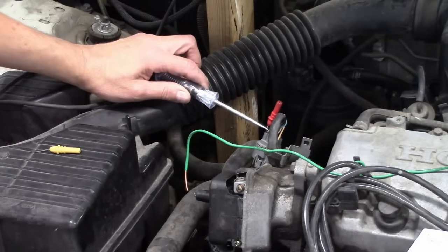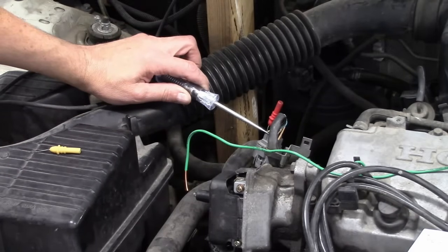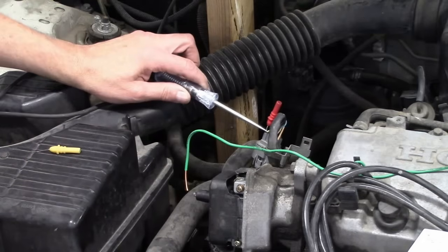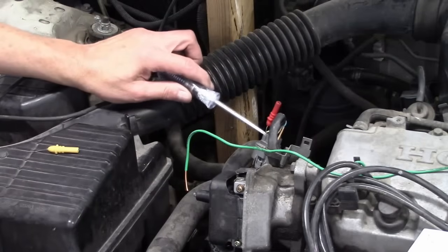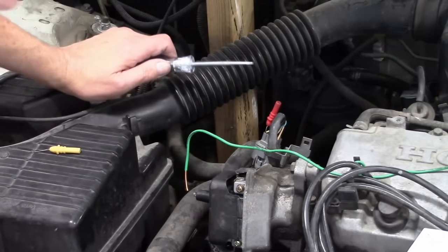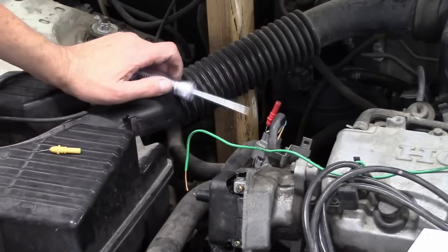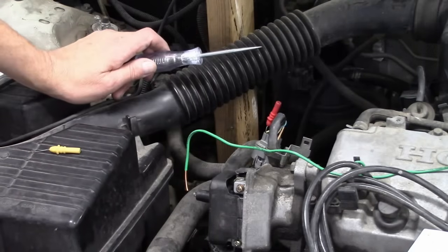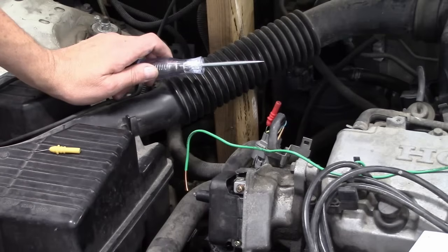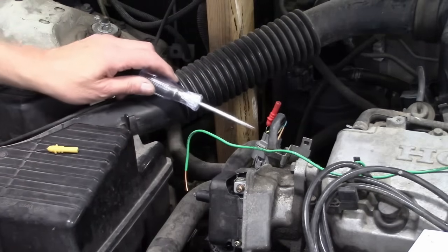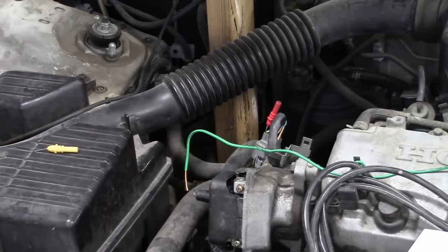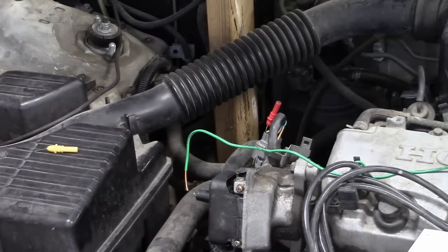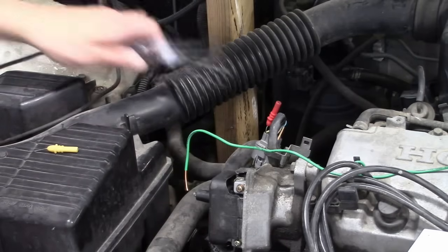So again, there may be other factors with this where I can't do this. On a typical non-distributor ignition, this would cause that spark to jump. So either the coil is bad or there is more complication to this system. I guess it's possible that grounding it on this design, maybe the PCM grounds it. I highly doubt that. I may just go ahead and try that, but I'm going to move my test light over to the battery negative, so now I could ground that signal out.